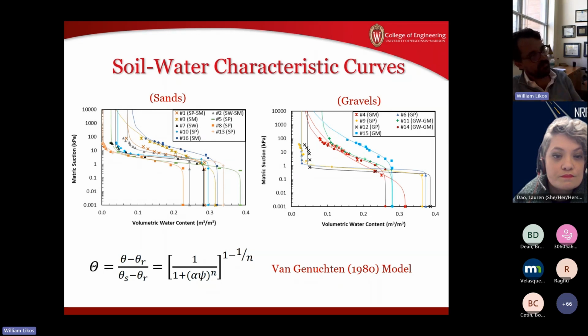There may be some effects at relatively high suctions, way up here on the curves, but at these very high suctions, we're talking about interaction between the water and the mineral surfaces, where mineralogy does play a more important role. But the size of these materials and the size of the pores that we're dealing with, this is about water that's in the larger pores. It's not about that surface adsorbed water. And so I would be very surprised to see any effect of, let's say, granite versus limestone in terms of what we're looking at here.